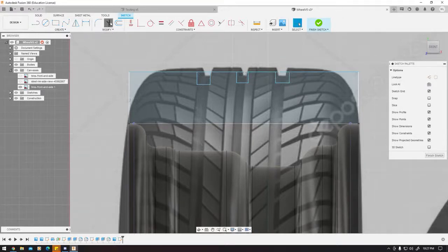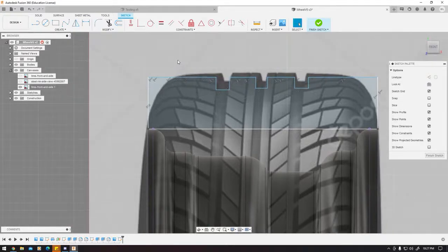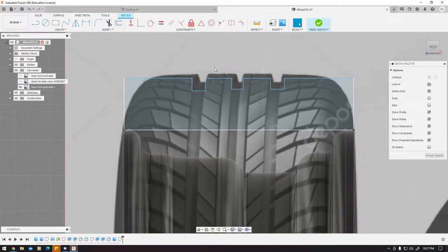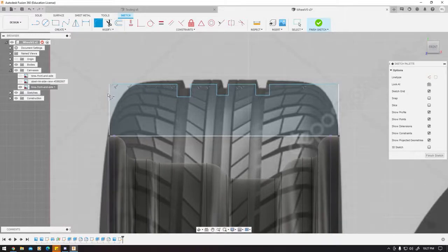And I can start using trim to cut off the excess. And you can press F for fillet, but that won't really work because it's a sketch, so you have to go here up manually because it's within the sketch tools. And we can start doing what we need to do. So it looks more like this. And we can just do copy there, press enter, and I can repeat the fillet. So I'm going to do it for everything, for the indents.